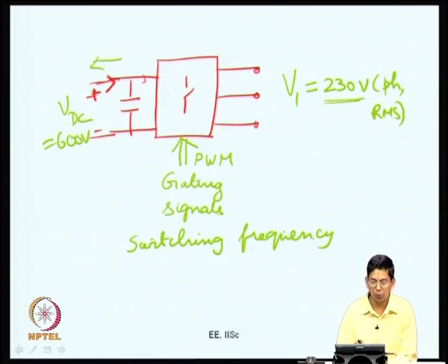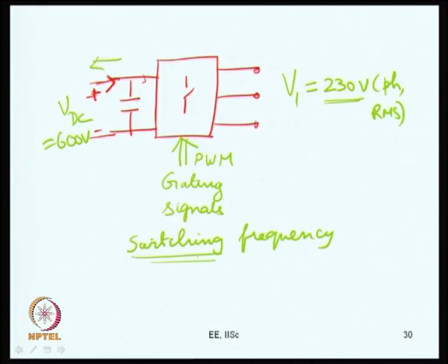So, that is how you have very little loss in a switch, whereas while a switch is undergoing a switching transition, both the voltage and current could be substantial simultaneously, and this produces a certain amount of switching power loss over that interval. So, a certain amount of energy gets lost every time you switch the converter. If you are talking of a high power converter, the switching energy lost is going to be much higher. So, the overall power is the product of the energy that you lose in every cycle multiplied by frequency.